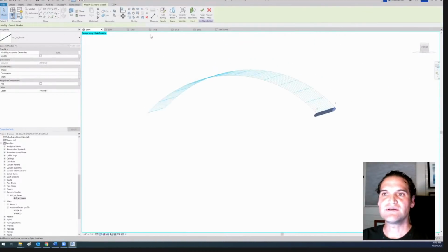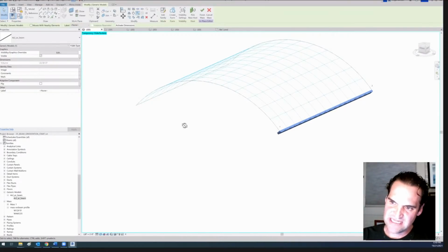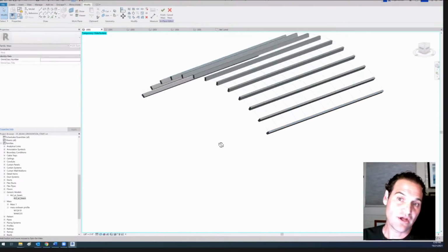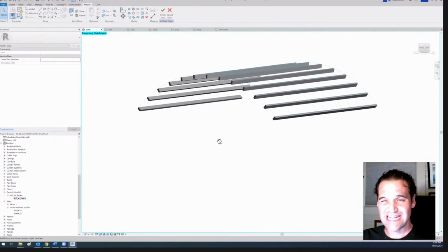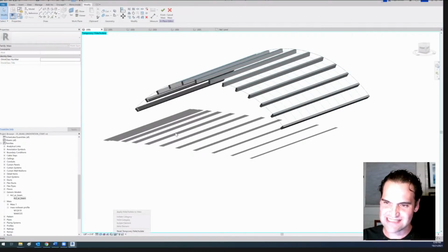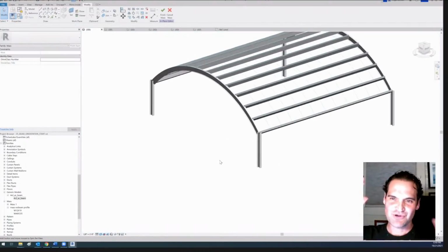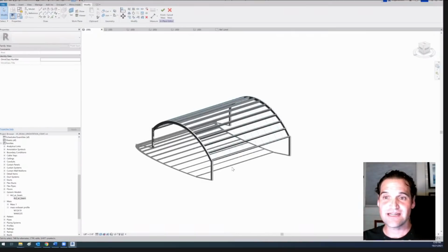Then you can activate your repeater, and it will place the beams with the flange tangent and the web perpendicular to that surface. So you don't necessarily have to play the rotation game. So this is kind of the manual way of doing it. In the book, I actually show you the Dynamo solution. Either way, it can kind of get you there.